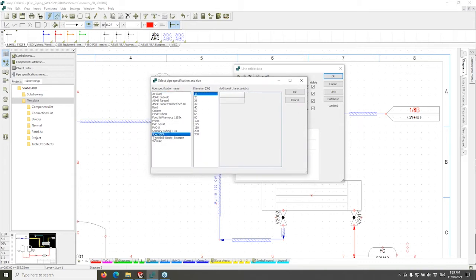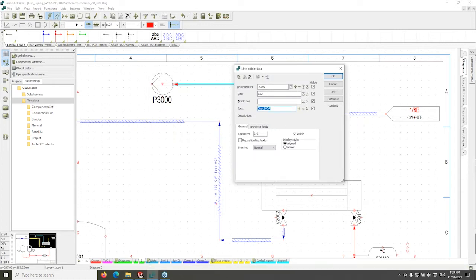I'm going to go with a spec named here spec 10CA, and I'm going to go with a 4-inch or 100 millimeter pipe. I'll click OK to that, and it fills out all the information there for me. Okay. And then I can put in some more process specific information, like HW for this is going to be hot water. If I want to put temperatures and that kind of thing in here, I can. What type of insulation is it going to have? These can also be drop-down menus that you can create as well.